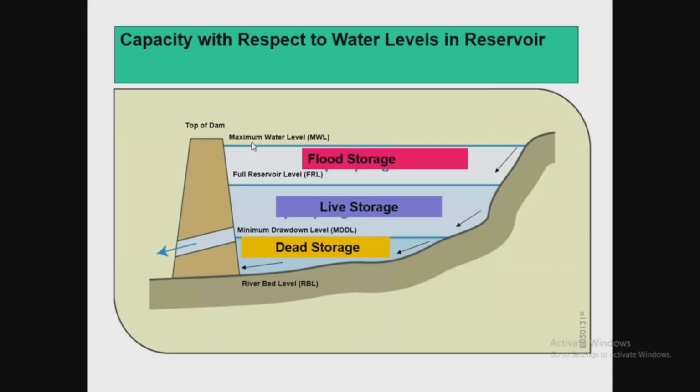Okay, the full reservoir level is that level which is between the minimum drawdown level and the full capacity level of the reservoir. Now, this is a very important level, because it gives the live storage capacity of the reservoir, or you can say the useful storage capacity of the reservoir. This is the storage from where we allocate water for irrigation, for power generation, for drinking water supply, and a number of other benefits. We allocate water from this storage only.